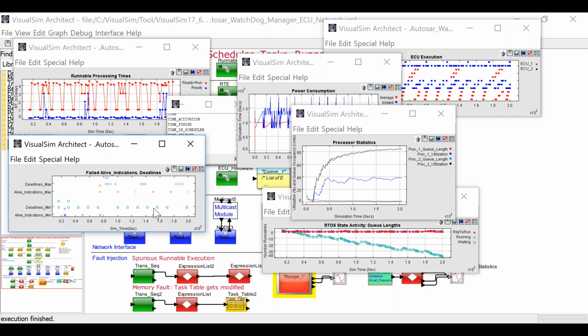So the minimum deadline is required so that the diagnostics or tasks do not arrive too far ahead at the processor, which means you're just going to wait idling in the processor as opposed to arriving exactly at the time that it's expected to. Why is this important? If I'm running on a GPS, I might want the data at a particular time point in my design. If for example, I'm braking, I don't want to use an earlier data, I want the current data. So it's important that it's not just a maximum deadline, but also a minimum deadline is incorporated.